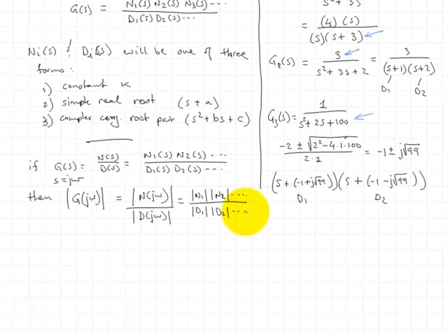So you see for the magnitude response, if I can efficiently determine and plot the magnitude of my three types of terms, then I'm just going to assemble those when I calculate the overall transfer function. It's even further simplified than this, though, because you might still say, oh, taking quotients and products is going to be complicated, nasty business, at least for a hand computation. And that's where drawing these plots on a log scale really comes in handy.